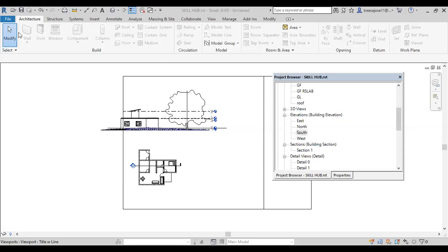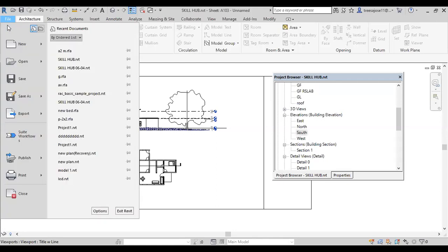Okay, for that, how to export it. There are some points to be noted. Then we get all the layers and the system will generate very neatly. But the units may not be matched when exporting, so you have to select the unit properly. Then only we get the unit correct. Now, how to export our Revit file into AutoCAD.